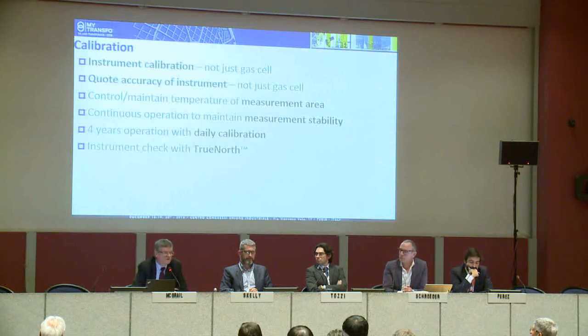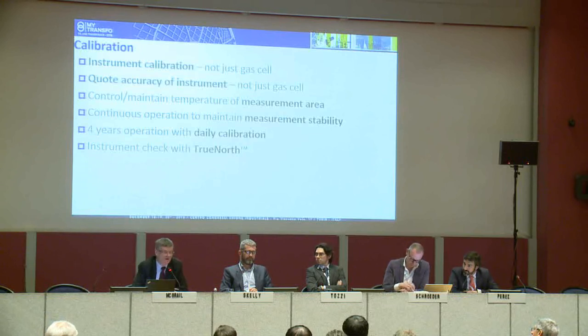To remove those, you need to have a filter. That filter is a maintainable device. It's consumable. If you don't have that device as part of your consumables, you're going to have drift due to the interference condensing on the mirror. So you have to be very careful.